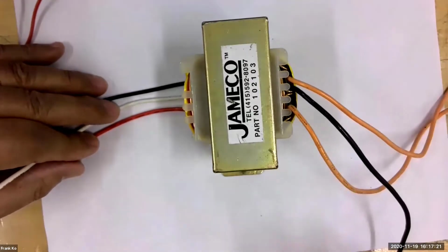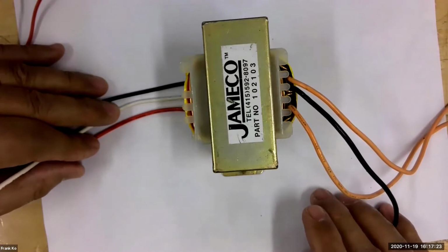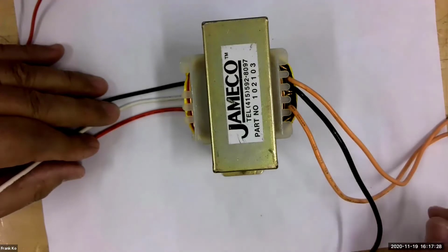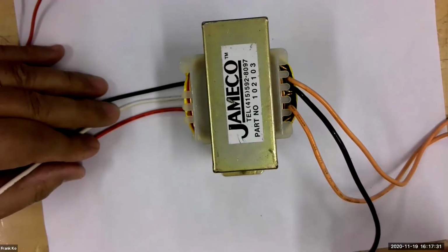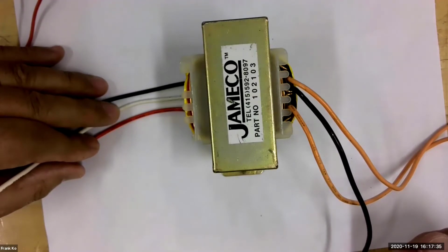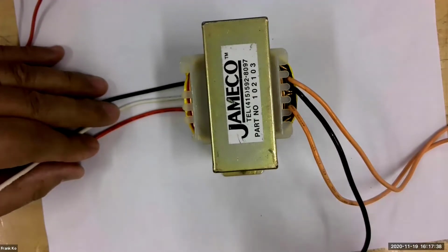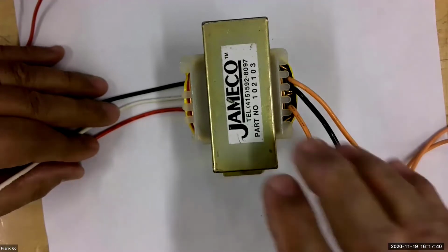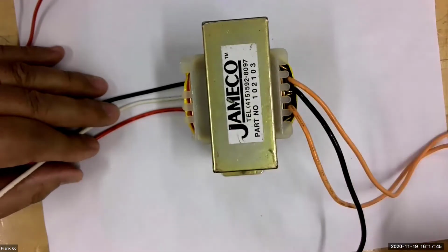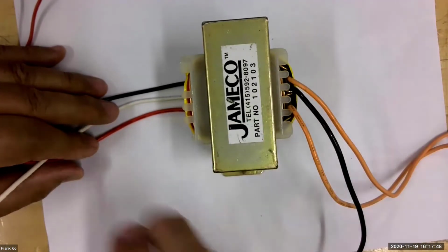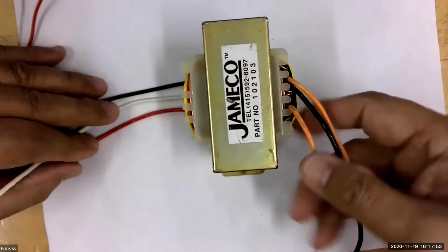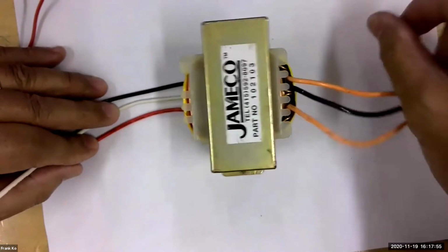Where those occur is if you have a friend visiting from a foreign country, and let's say they need to plug their computer into a wall outlet for charging their cell phone or their computer. But lo and behold, where they came from, the voltage was 220 to 240 volts, whereas we're only 120. So we're going to need something in order to allow them to plug in their devices to work. So we would put 120 volts on this side, and with a different transformer, we would have 240 volts on this side.